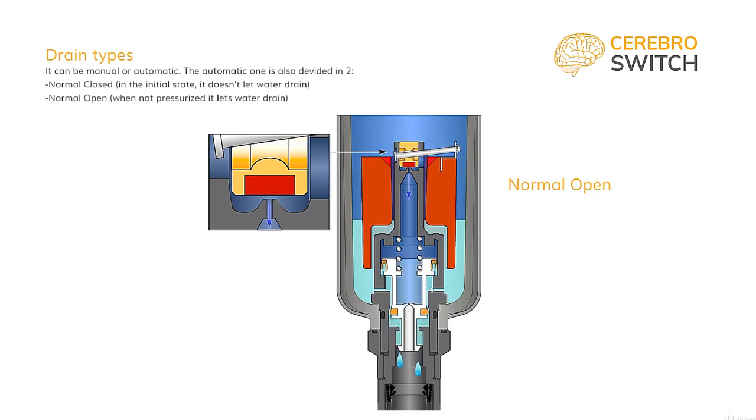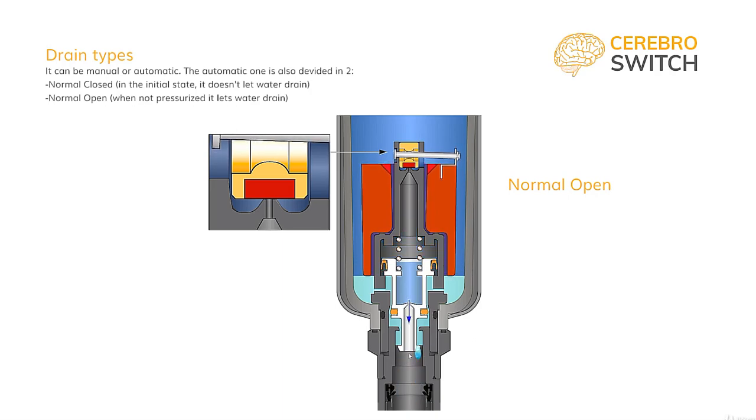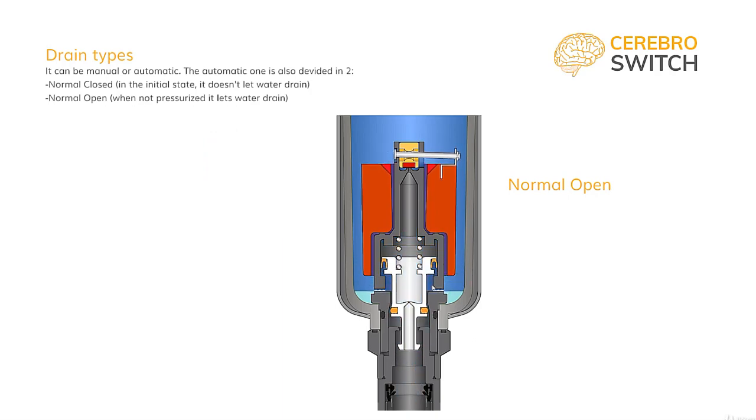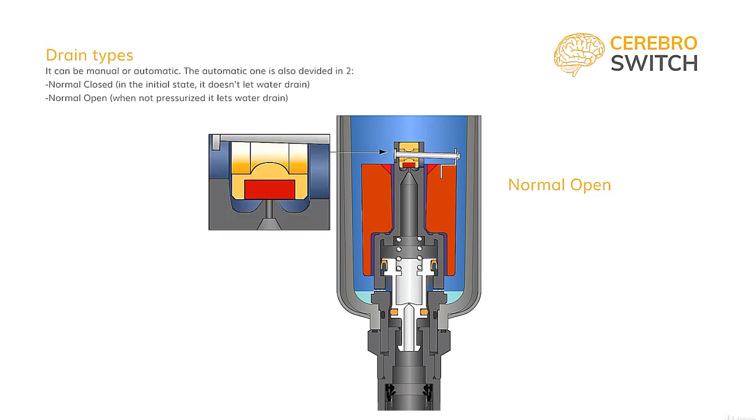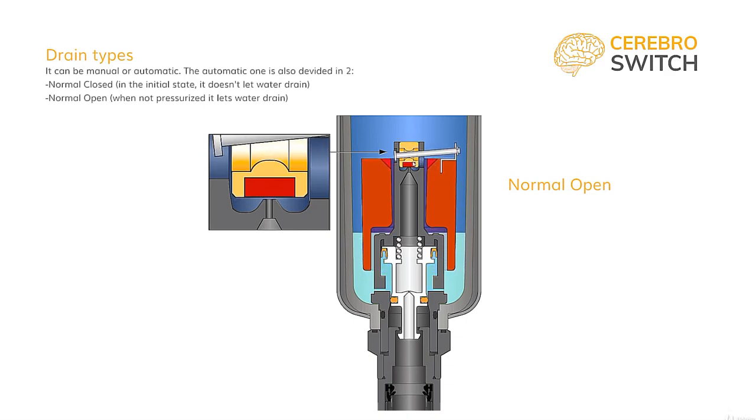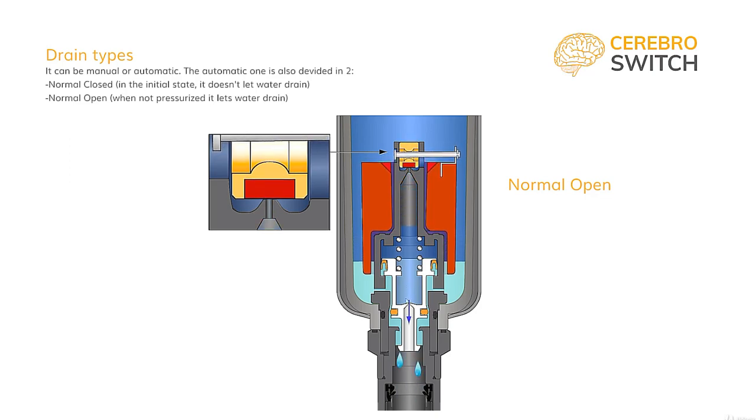Then, when the valve at the top opens, pressure will rush in to aid the spring, pushing the piston down. Afterwards, as before, upon water drainage, the valve will shut, and through the capillary orifice, air will bleed out slowly, keeping the piston lowered for a little while to give water enough time to fully drain. Finally, the pressure will raise the piston back to close the water drainage path.